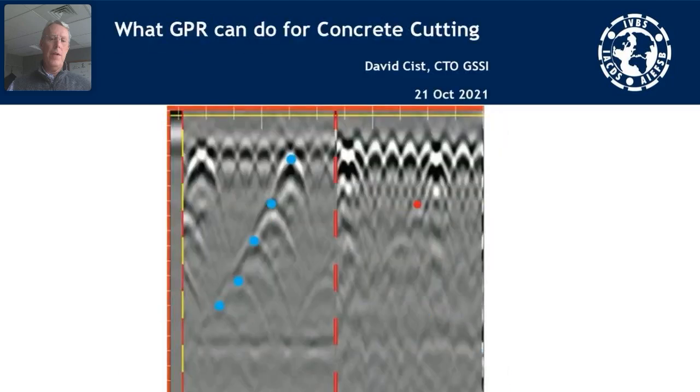This is one of the more subtle and important parts of ground penetrating radar, and this is where the service companies really are helpful. This is a scan, the same scan, but using a different polarization. If you take your antenna and you rotate it 90 degrees and push it along the surface, you get a different signature back from the radar scan.